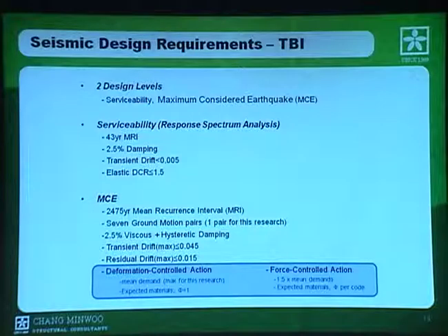And the guidelines for seismic design of tall buildings, TBI, and the LATBSDC talk about this issue, and require two design levels: serviceability and the maximum considered earthquake, MCE. For the serviceability level, response spectrum analysis can be used with a 43-year MRI. MRI means mean recurrence interval. The transient drift limit is set to 0.005, and the elastic DCR limit is set to 1.5.